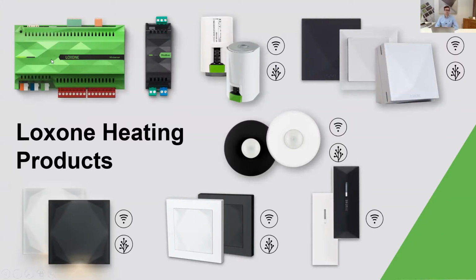Now, as always, we've got the Miniserver, brains of the system. This one here is an extension, and this is a Modbus extension. For anyone that doesn't know, Modbus is a form of communication, usually over either RS485 or it can be over IP as well, where you can talk to certain industrial components. Now, Modbus is very old, but still very common.